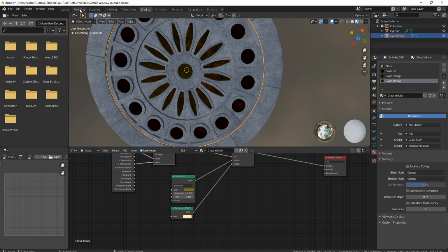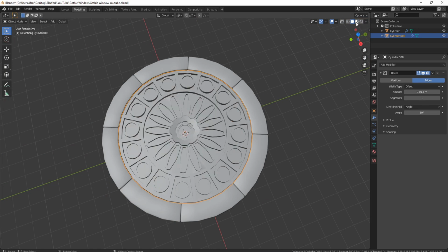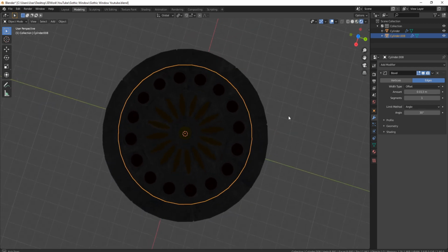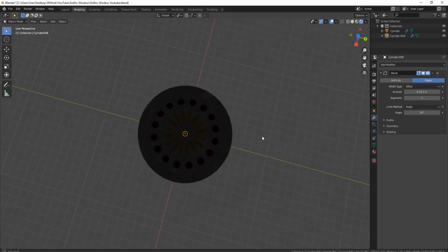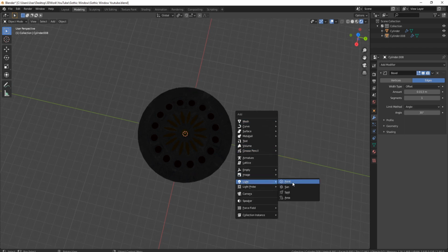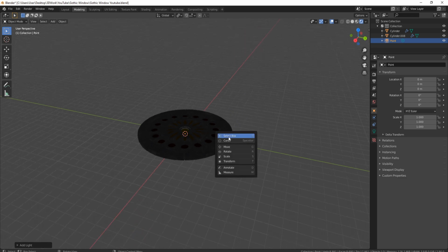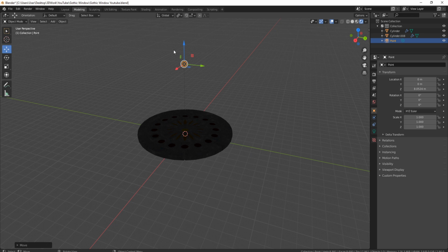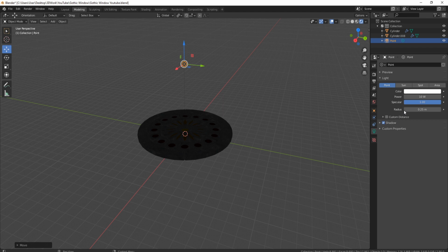Alright, so now let's go back to modeling. Let's press tab, put it on material, and I think we can put it onto Eevee. You won't be able to see anything at the moment because we need to bring in a point light. So light, point light, bring it in, shift spacebar, move, bring it up, and now let's make this point light really, really bright. We'll come over to our actual light over here. We'll turn down the radius first of all, because we will need the radius down for the next part of this, and then let's put this on something like 1000, and there you go.